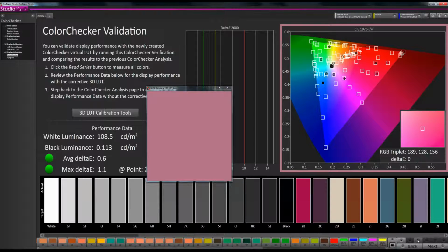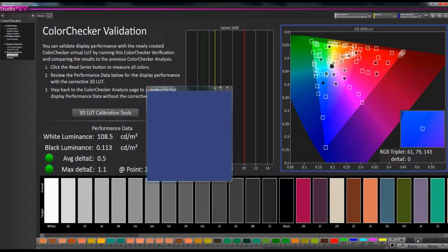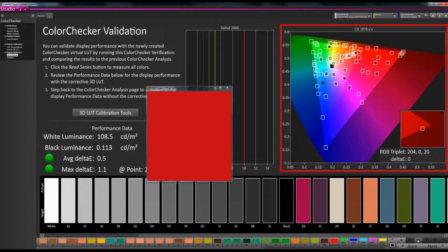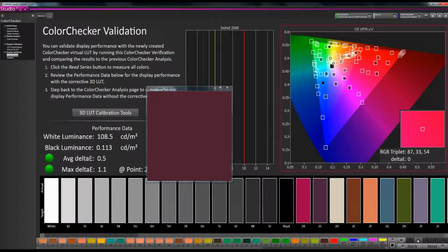Okay, so here's another question. Why does CalMAN initially default to a gamma formula of setting BT1886? BT1886 is the gamma specification created by the ITU in 2011. Before that, there was no real specific gamma specification. When we were all using CRTs, they had an inherent gamma of somewhere between like 2.3 and 2.4. So it didn't really matter.